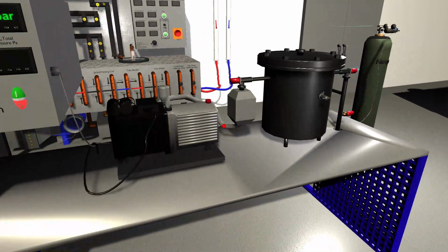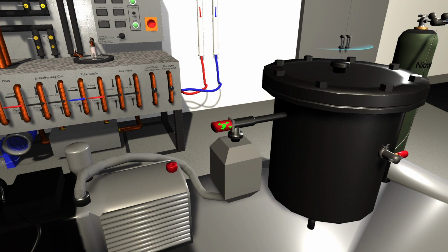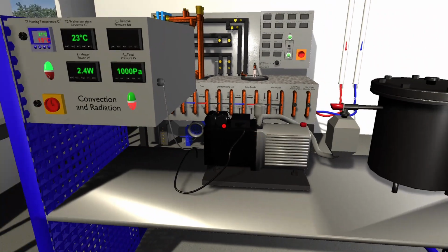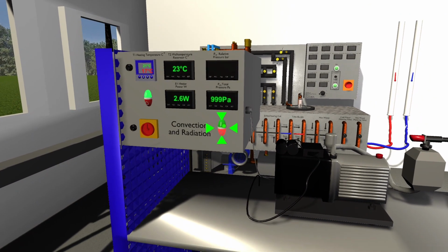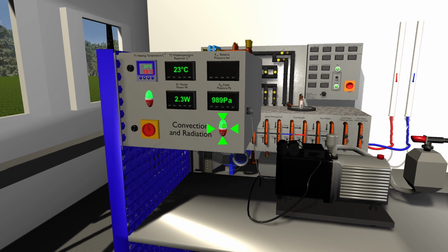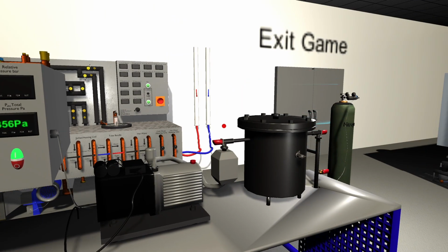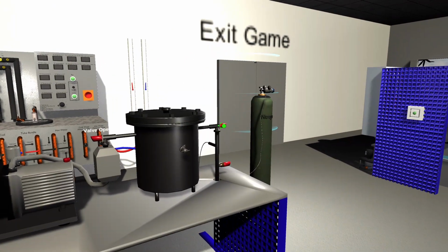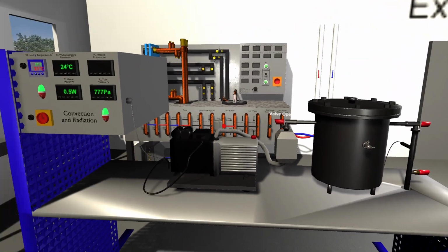Now I have a vacuum pump here. And if I open that valve connected to the vacuum pump, you can see a valve open pops up. Right now the pressure is 1000 Pascal, close to atmospheric pressure, okay? But as soon as I turn on the vacuum pump, you would see the pressure decrease because we are sucking out all the air inside the chamber. You can have nitrogen in the chamber, you can have air in the chamber, you can have it run under vacuum. Right now, even though I have connected the nitrogen tank, the valve is not open on this side, so there's no nitrogen flowing into the tank, and I'm just emptying the tank.